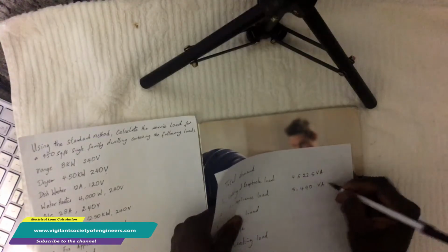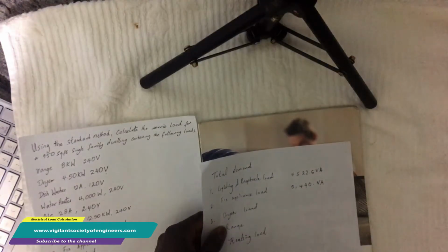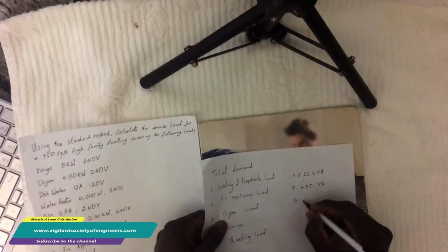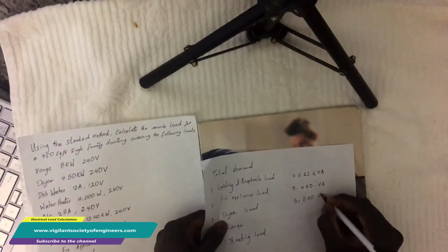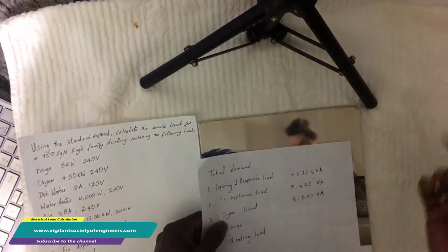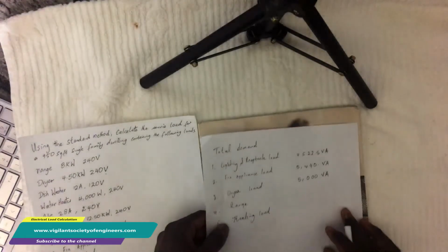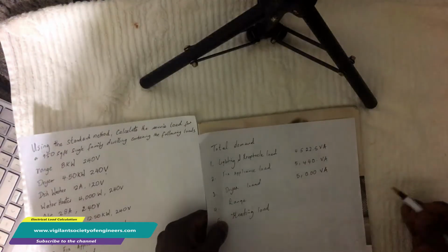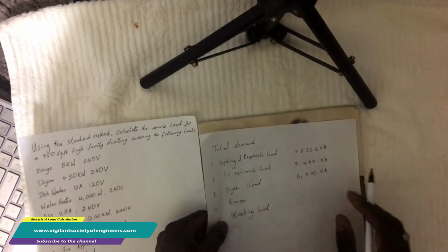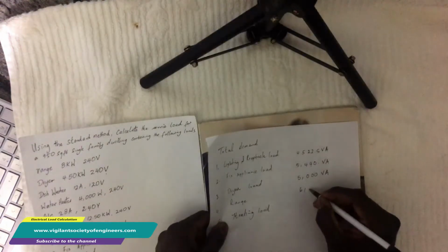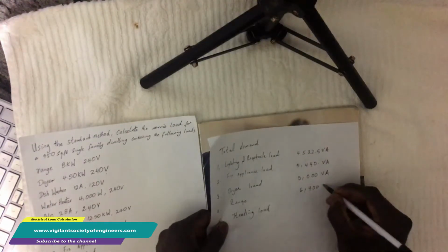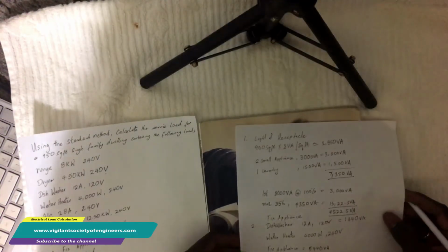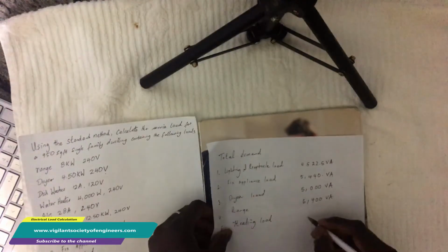Then we're going to take into consideration the minimum for the dryer load, which is 5,000. Remember the demand per dryer, even though the value was less, as it was 4.5 kilowatt. And the range is 6,400 VA, and the heating load, which was 12,500.